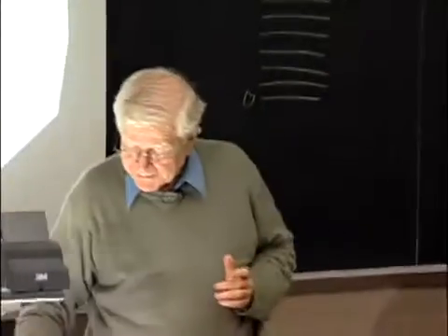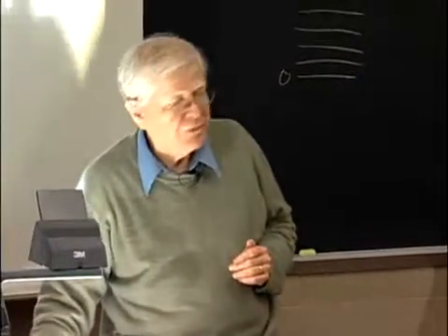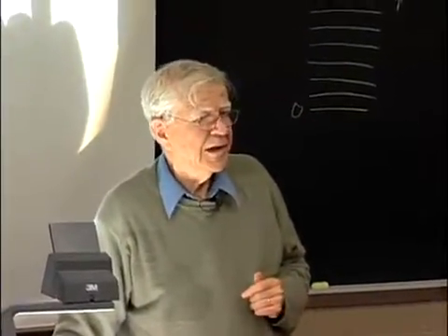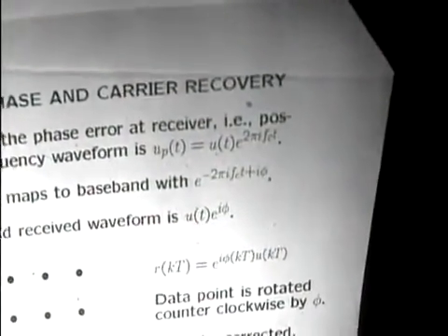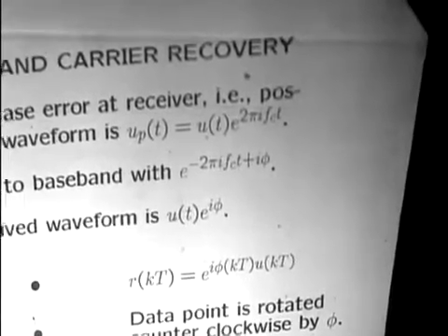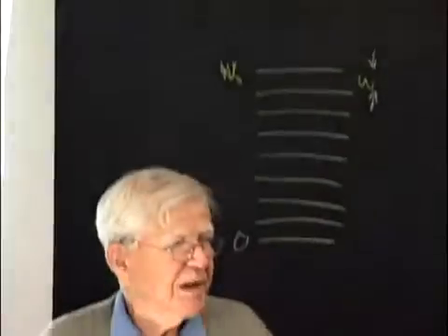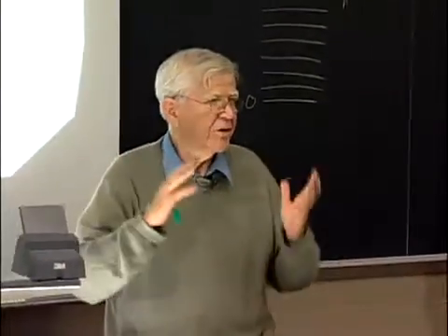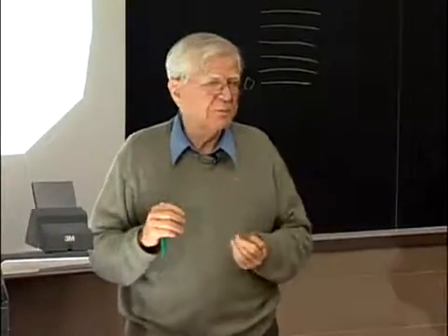If all the phases are positive, then you know that you have to change the phase of this carrier one way, and if all the phases are negative, you change it the other way. Now, why does this work? It works because these clocks are very stable clocks. They wander in phase slowly. I mean, you can't lock them perfectly.